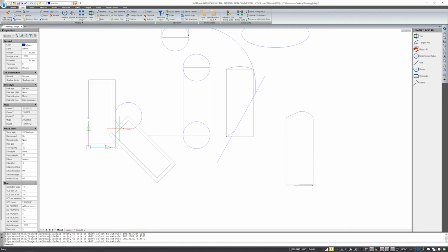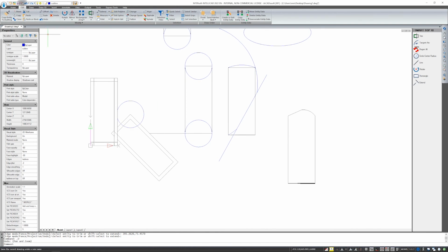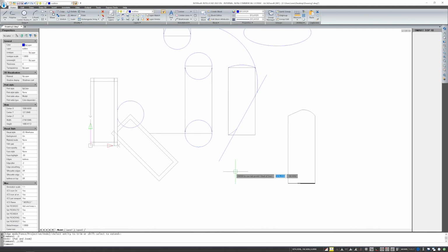But this Shift button also still works when we start drawing. If you draw and you do not have Ortho turned on, then if you press Shift, the Ortho turns on automatically. Now please note, if I have Ortho on and I press Shift, it will be switched off for a while. So remember, Shift is a special button that changes our options a little while drawing or editing. And it comes in handy very often, so I suggest using it.